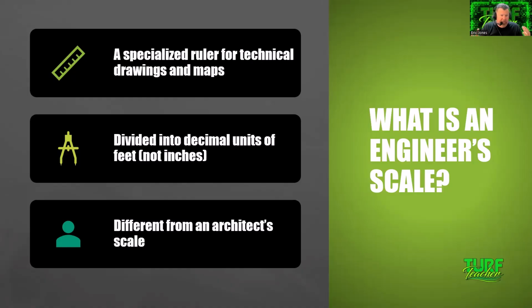Now, as an irrigation and landscape designer, we're going to use that architect scale for our construction details, more than likely. We're going to use the engineer scale to do the site plan and the total irrigation plan, something that's bigger. If we're using architect scale, our drawings are going to be a little bit bigger. So that's why we use them for details and stuff. If we're trying to shrink that property down and fit it on the paper, that's why we're using these engineer scales.